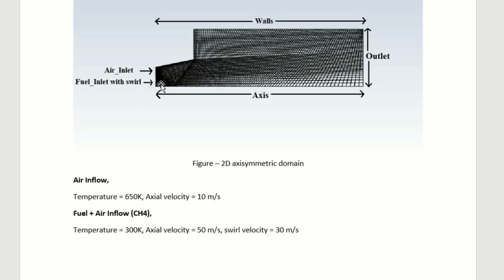The simulation will be carried out at 0.8 stoichiometric ratio, that is, a lean combustion simulation will be generated. Based on the 0.8 stoichiometric ratio, there will be a considerable amount of mass fraction for CH4, N2 and O2, which will be used as reactants for our simulation, and that can be calculated using a chemical reaction. When we write a chemical reaction, based on our stoichiometric conditions, we can calculate the mass fractions for our reactants as well as for our products. We will simulate this condition in ANSYS Fluent GUI, and understand how we can combine the premixed and non-premixed models into one model, that is the partially premixed model.